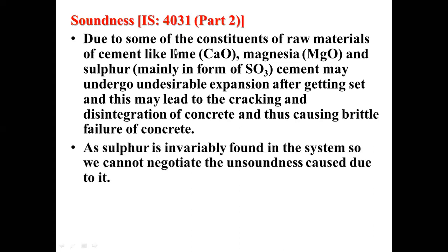If excess lime is there, we conduct the test using the Le Chatelier apparatus. If magnesia is there, the apparatus we use is the autoclave. Autoclave: this is an important question they ask for magnesia. If excess magnesia is present in the cement sample, we have to go for the autoclave test, and for lime we go for the Le Chatelier apparatus.